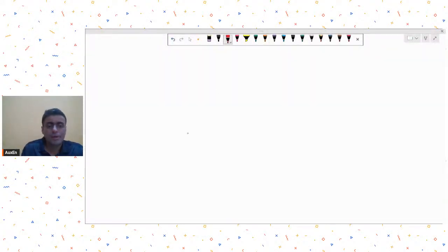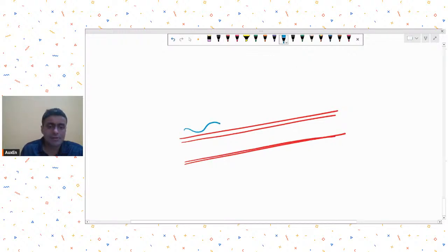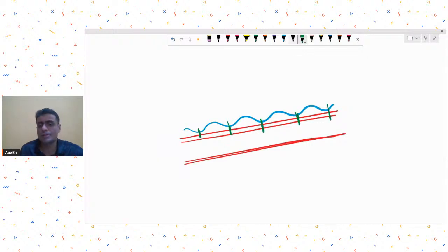Now, usually speaking, if I were to draw a plan view for this, okay, let me draw a sectional view. So this is my purlin, let's say Z purlin, and on this your sheeting is going to be attached like this. So usually all the troughs will be connected. That is quite obvious. So these troughs will be connected.